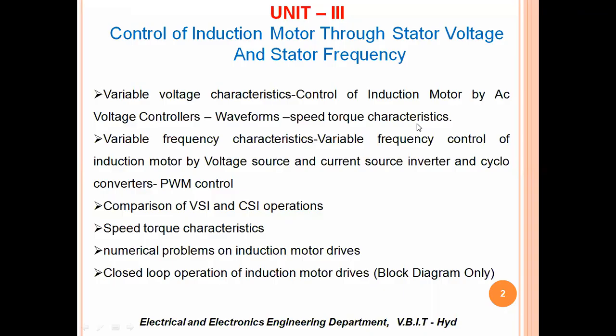For variable speed control, induction drives are the most used drives nowadays, and they have a large number of applications, like fans, blowers, mills, cranes, conveyors, etc. These are the dominant speed control drives in use today because of the advantages they have when compared with DC motors.